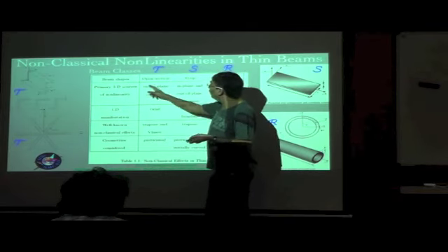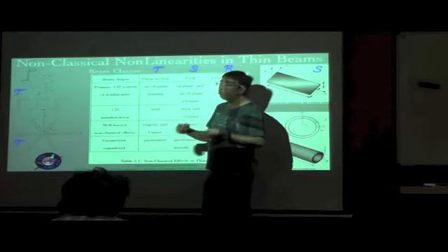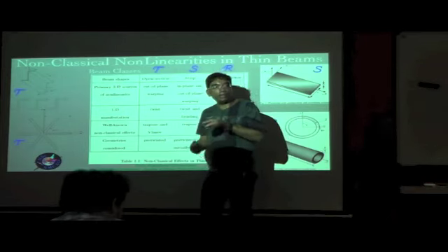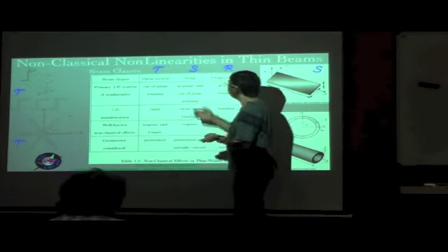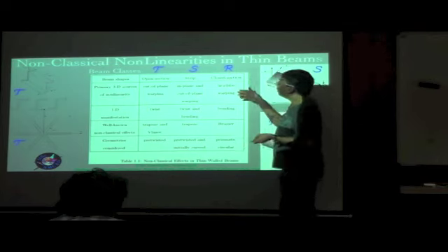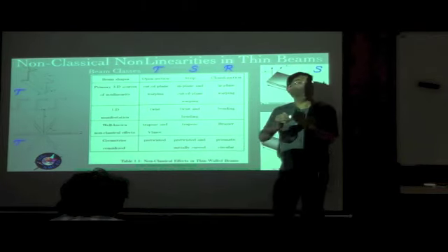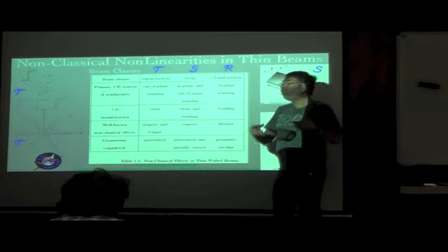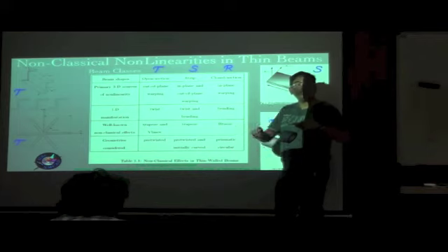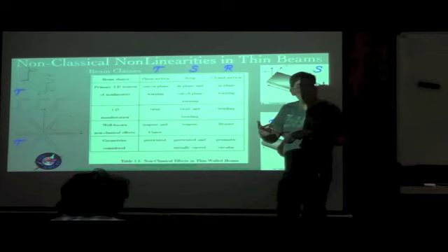So it is that which we are talking about, out-of-plane warping, or what we refer to as the W1 component. In the case of the closed cross section, it is the in-plane warping. Again, it was demonstrated for you in the Brazier effect, where a circular cross section became ovalized, or when you have a tensile load, for example, you can see that there is flattening because of the Poisson effect. So all those are in-plane warpings.